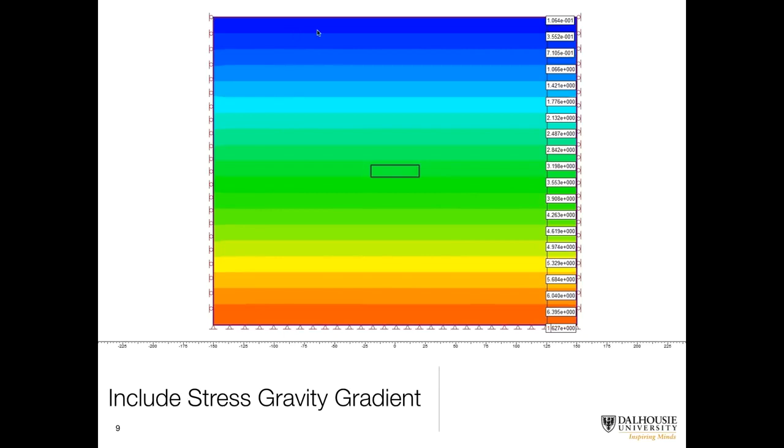And that is because when we carry out the simulation and apply gravity loading to the model, the elements are going to move downwards under the load of gravity a little bit. And if these were fixed in y, they would kind of hang the model up, pulling it upwards, and you get some stress concentrations and some shear stresses like this. It would want to form a bit of a trough, and that would cause a stress distribution that you just don't want. You really want a nice uniform simulation as if this boundary wasn't here and we were looking at the ground in its full extent.